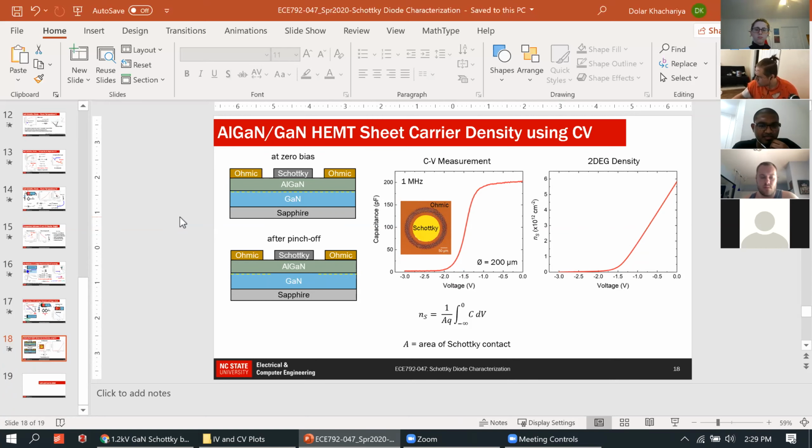So in the structure that Dollar is showing you here in the slide, he's assuming that you've made a nice two-terminal Schottky diode test structure. But you only have data for transistors that are 3 terminals. So you have to choose the right terminal to find that Schottky diode behavior. Where would you look in a FET data spreadsheet, where the measurement data is collected, to analyze the Schottky diode?